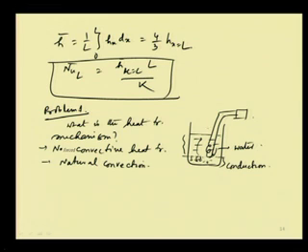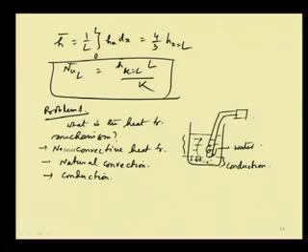So, there is a combined mode of heat transport here. Part of the fluid is being heated up by natural convection, and the bottommost part of the fluid is getting heated up by conduction. Therefore, if some of you have noticed, if you switch it on and take out that heater gently, you will find that up to the depth of the immersion heater it is heated up, but after a certain depth the water is cold. So, we have to do some kind of stirring to have uniform heating finally.